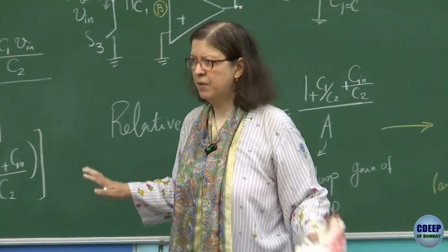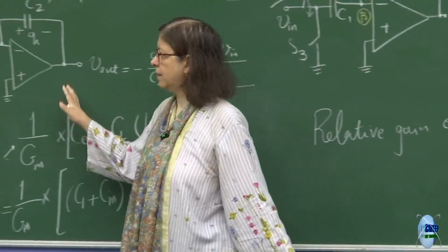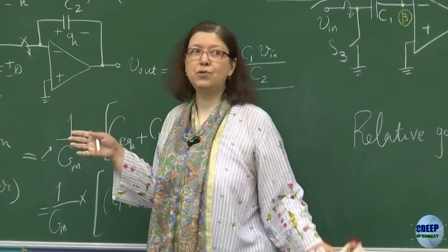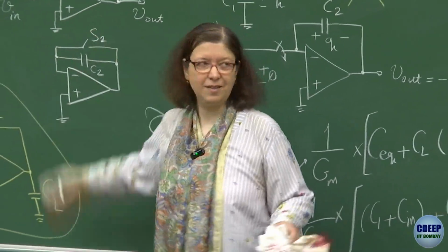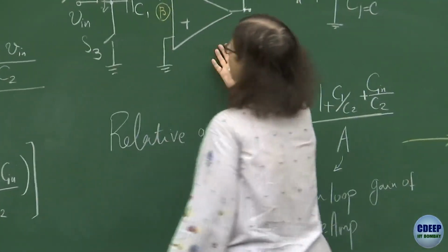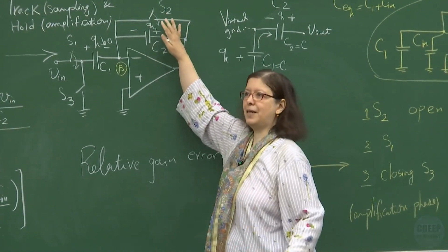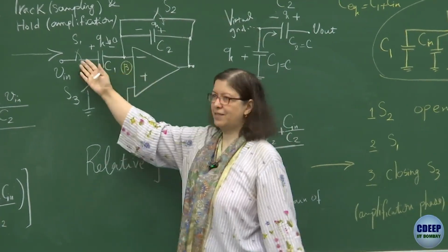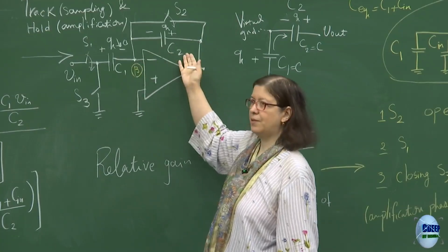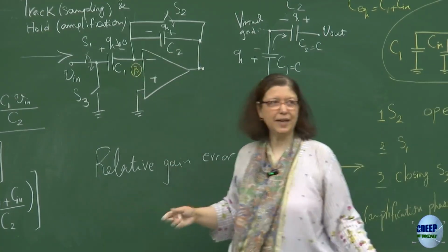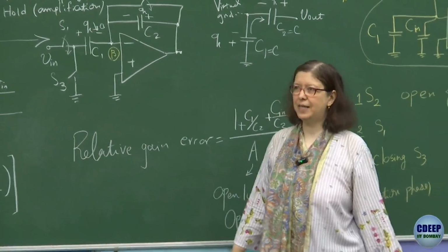So effectively, we have almost covered the entire chapter. There is one extra section on the switch capacitor integrators. So the integrator is the same as this configuration, and this discrete time is similar to this configuration, only what you do is that you don't switch C2. Let it just accumulate the charge over time, it's an integrator. Like one resistor here, which is now replaced with a switch cap, and here you have a capacitor. So it's very simple. Now, in fact, that part is simpler than what we have discussed till now. So please read that part as well.